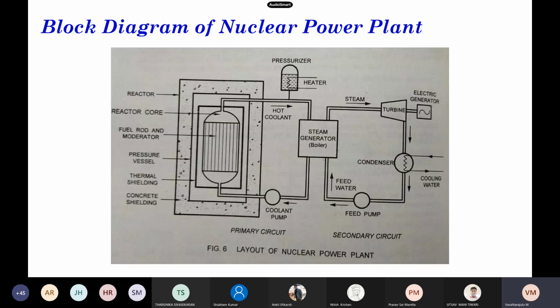Whenever the load on the reactor changes, the coolant temperature as well as its volume changes, and this causes a pressure change in the coolant circuit. Whenever the pressure increases, water flashes into steam, and this results in disruption of the safe working of the reactor, so this circulation has to be maintained at pressure, and we have to be very conscious.